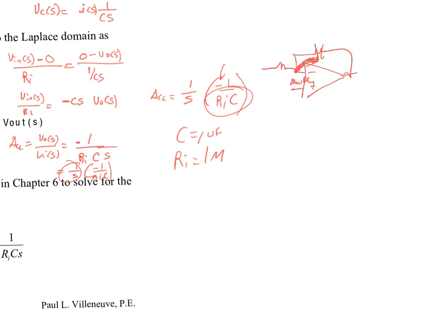Add another capacitor? You would usually put a compensating resistor in one of the terminals. I can't remember which one it is, but it's usually an R sub C. You have to adjust it to get the DC offset to go very small. They do make fancier ones called chopper stabilized op amps that actually will automatically adjust their parameters to get it to be 0, but those are pretty hard to find. What would you do in the real world if you're not going to be sitting there tweaking your compensating resistor?